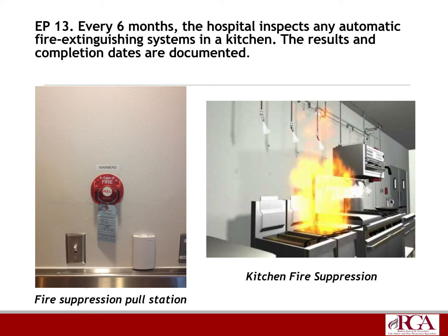So it's important that you have this specific test performed, and that it's done properly. In addition to this fire suppression system being activated, your contractor is going to make sure that the fuel source is shut off. That is your gas fuel and electric source. So anything that's powered up to the system shall automatically lose power, and your fuel source, your gas shutoff, because it's integrated into the system, should also automatically shut off. So that should be verified.